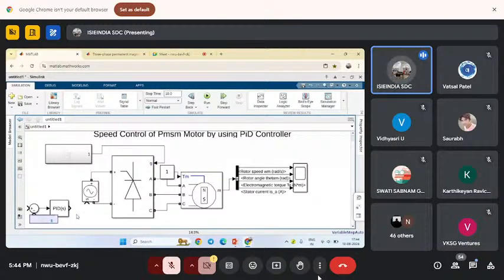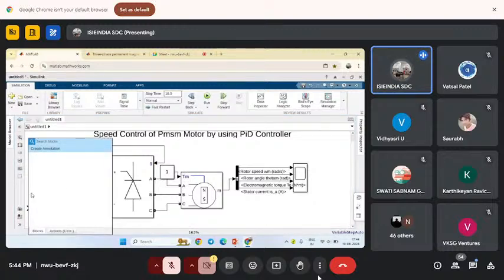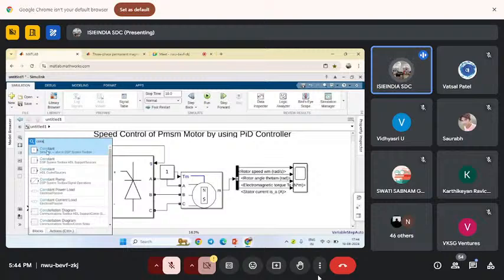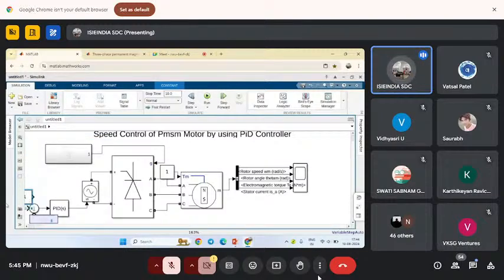And after that we have reference speed. So this is to be connected to the controlling voltage, and we have a reference speed. We need to go for the constant and apply the reference speed there. So I'm here taking the constant value. You can go for the drive cycle also if you want.